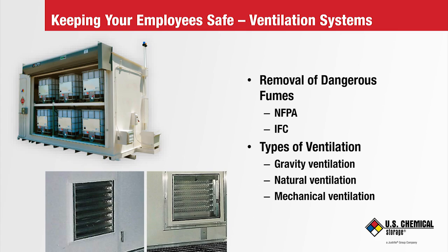Now we'll talk mechanical ventilation. It starts again with a low-level vent becoming the air intake, and the second low-level vent on the opposite wall acts as an output, similar to the gravity ventilation solution we already talked about. Here, outside the second vent, is installed a vertical stack or duct up on the exterior wall.